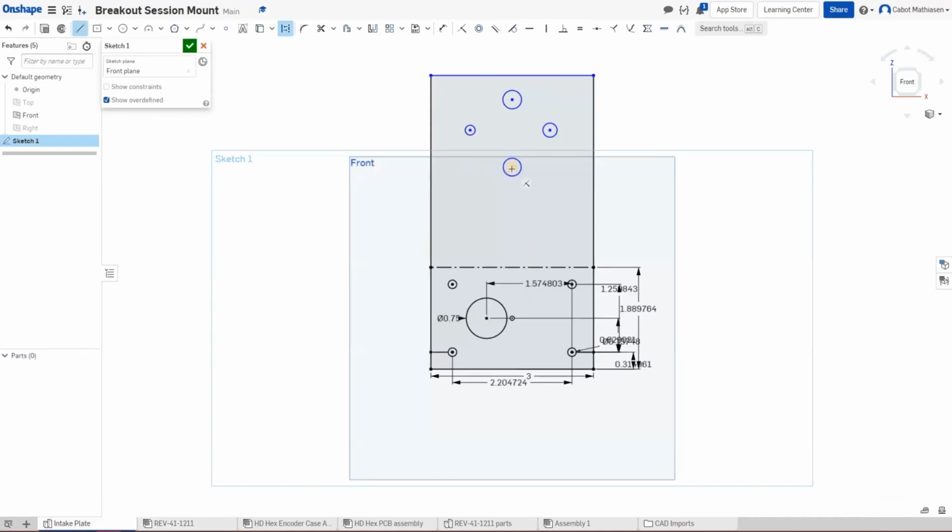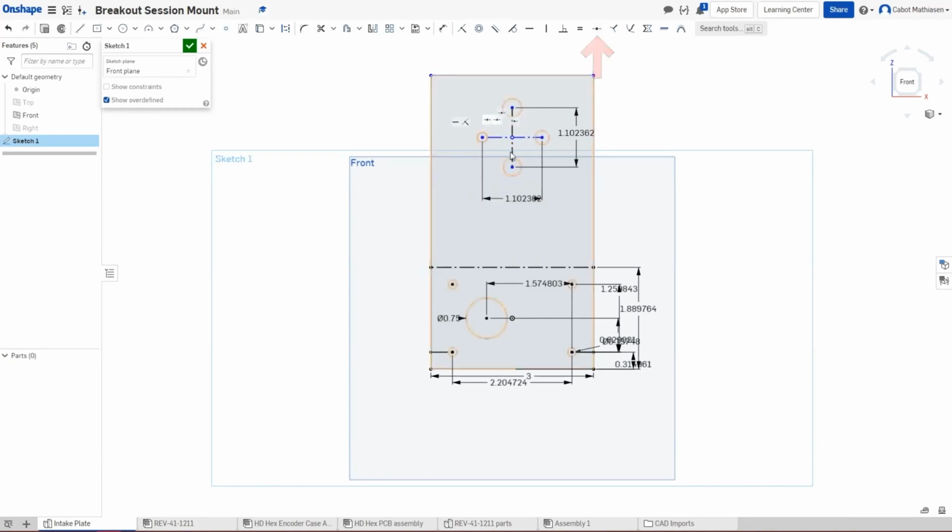Now I'm going to put in some construction lines to dimension these the right length. So I'm going to dimension out both of these. You could use equals, but I decided not to. Now I just put a point in the middle of it. It hovered a little yellow box, then you click on there, so that's how you know it's in the middle. And then I clicked on that point and on the other line. Then I used the midpoint constraint. The midpoint constraint is used so it will go directly in the middle of both because I did that point. So now it is perfectly symmetrical.